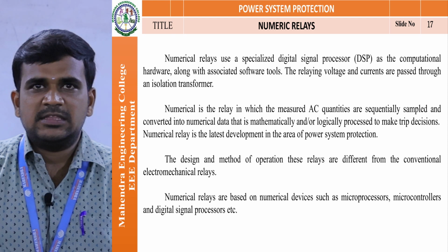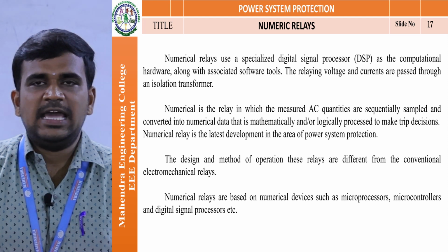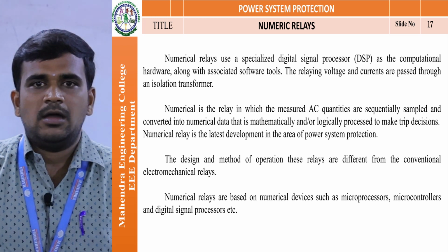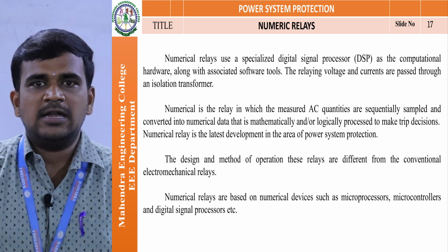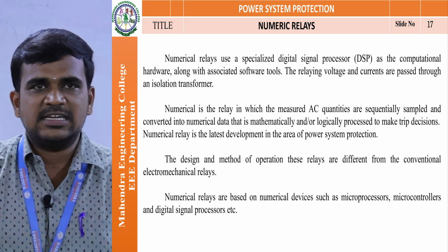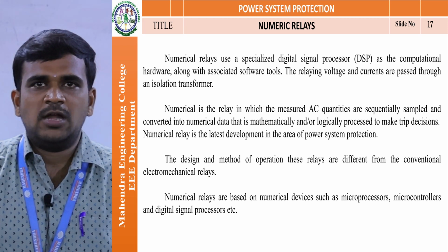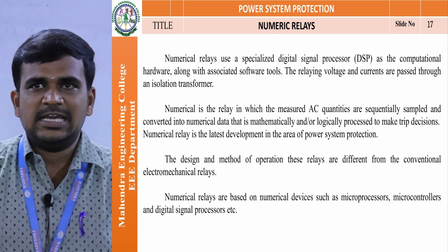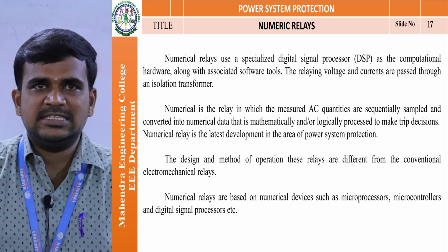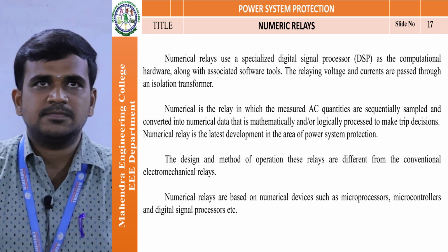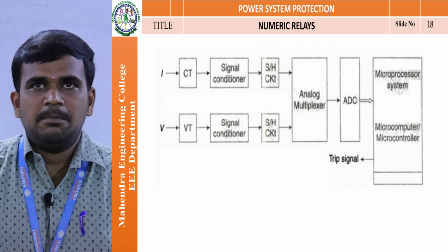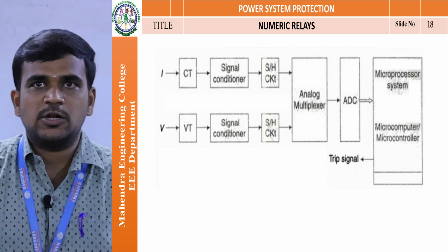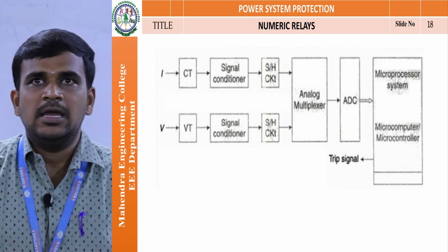The design and methods of operation of these relays are different from the conventional electromagnetic relay, because here the output is very smooth and a high quality signal. Numerical relays are based on numerical devices such as a microprocessor, a microcontroller like a PIC, and a DSP, digital signal processor, and so on. Here the major block is the microprocessor system, microcomputer or microcontroller system. This is the final block.